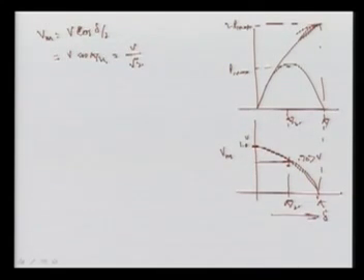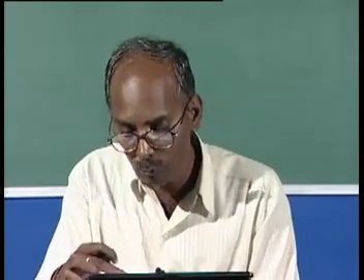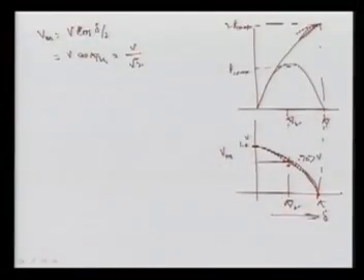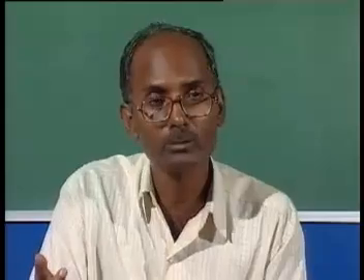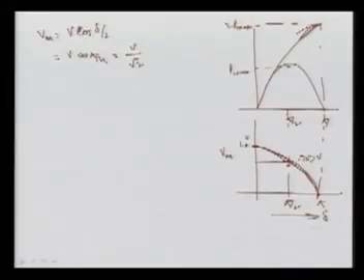So it is saying that when you achieve this, the voltage of the midpoint is going to be 0, and this is the decline in the voltage. Now, if we can maintain the midpoint voltage at its 1 per unit limit, then we can transfer a huge amount of power. So this is the limitation. Once you are throwing more power, means more delta separation, you can see the voltage magnitude of this bus, that midpoint, is decreasing.